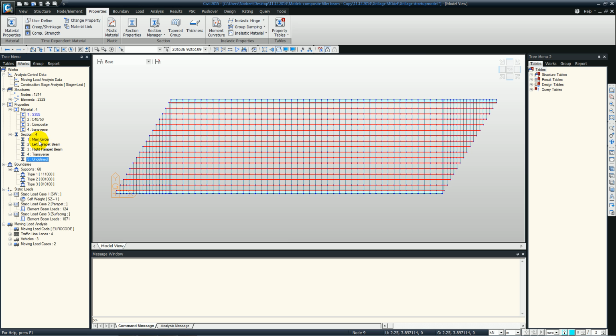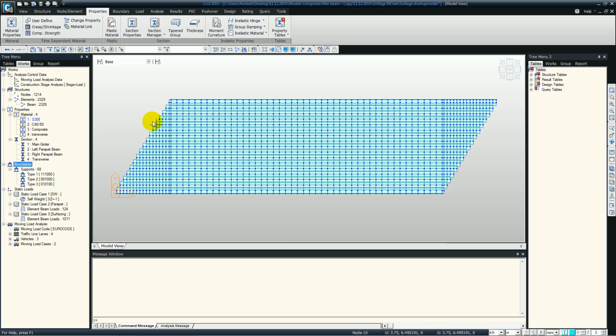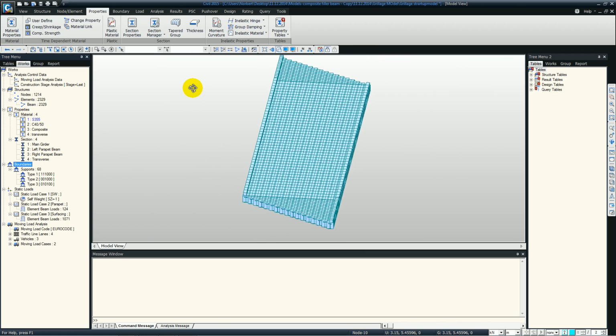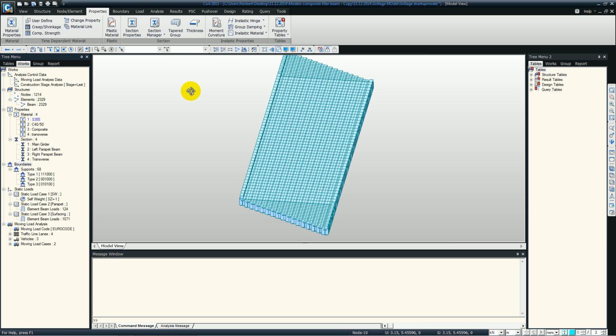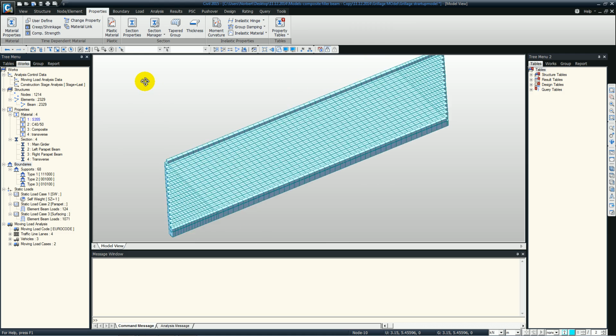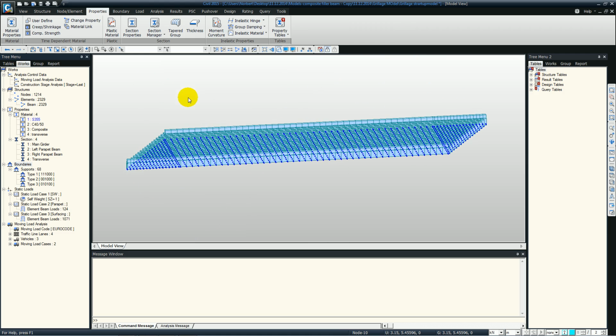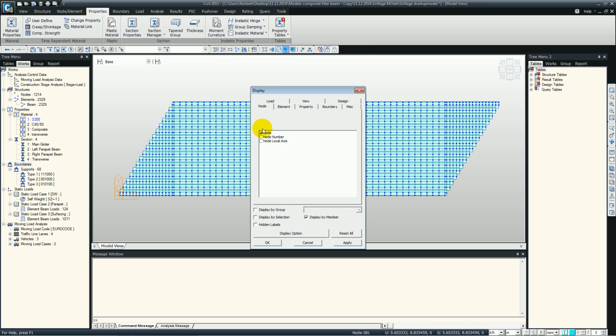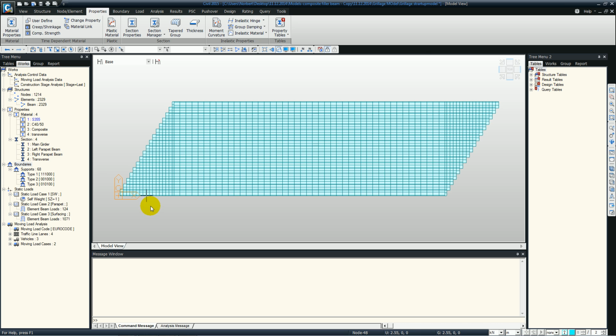Now we're going to assign this to the longitudinal element, so just simply drag and drop main girder onto the screen. Okay, so at this point you can see that we have our I sections with the concrete around them, and the model is completed. Okay, so next I'm going to generate, let me take off the node. So next I'm going to generate the construction stages.